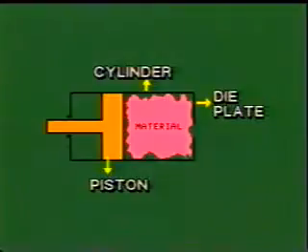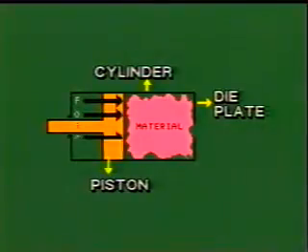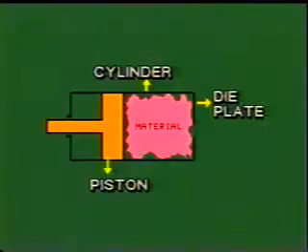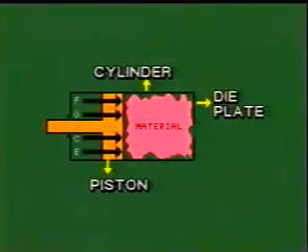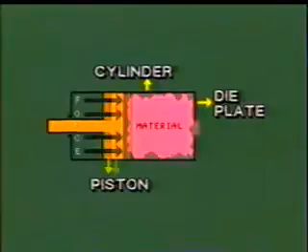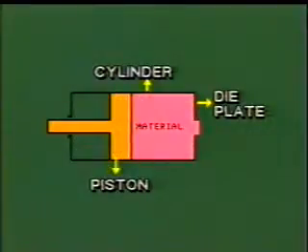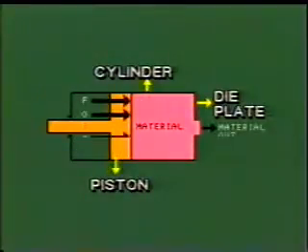The principle involves keeping the material in a cylinder. The material is pushed by means of a piston against a die. With the pressure force, the material is first upset to fill out the container and then emerges out through the die.